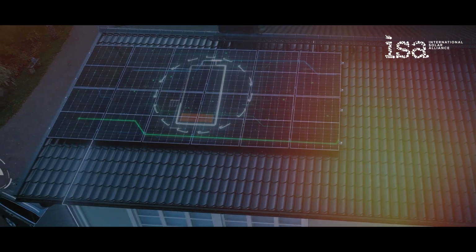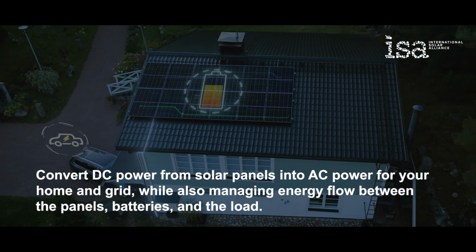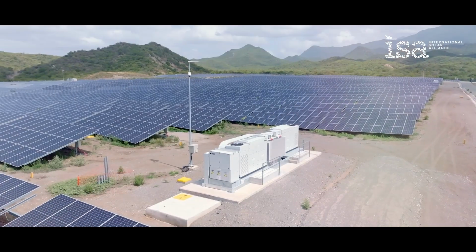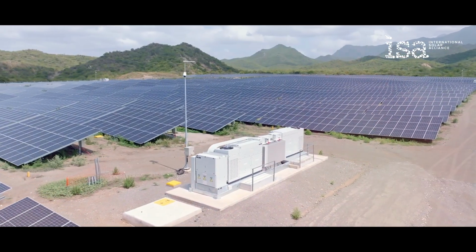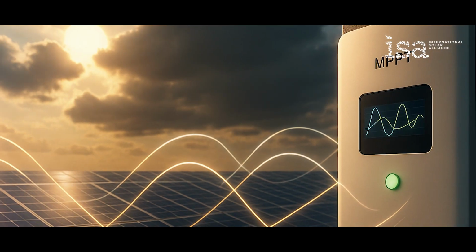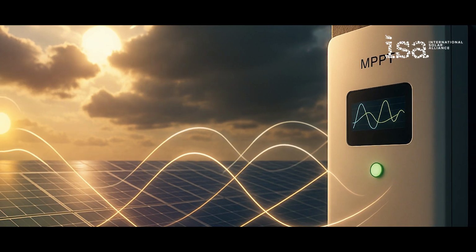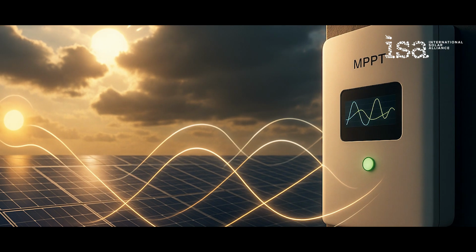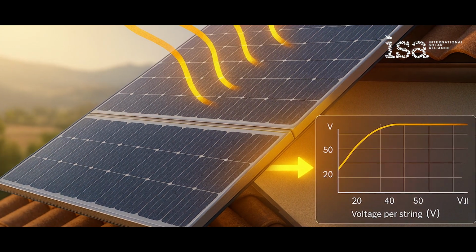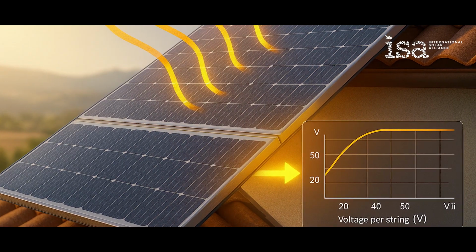The basic function of the inverter is to convert DC power from solar panels into AC power for your home and grid, while also managing energy flow between the panels, batteries, and the load. When connected initially, the power generated in the PV modules, corresponding to their wattage, travels to the maximum power point tracking (MPPT) device in the inverter in direct current (DC) mode at the rated panel string voltage, VMP, maximum power voltage. The most important function of MPPT is to maximize the electrical power output from a solar photovoltaic (PV) system.